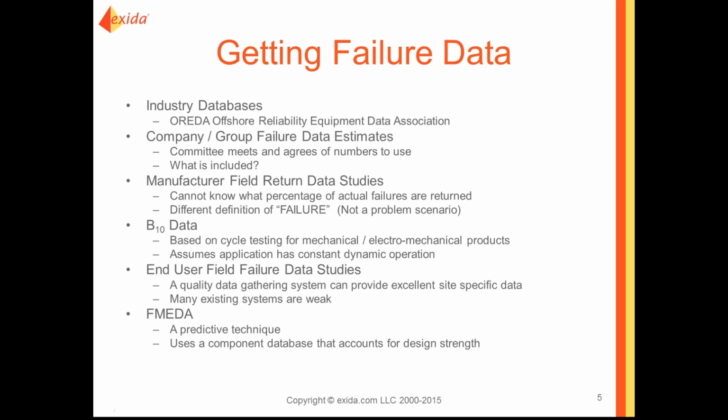So, for getting failure rate information, there's a couple typical areas, and they include looking at industrial databases, looking at publications by industry groups or within larger companies that might have their own guidance. There's field studies or return studies done by valve manufacturers or equipment manufacturers.